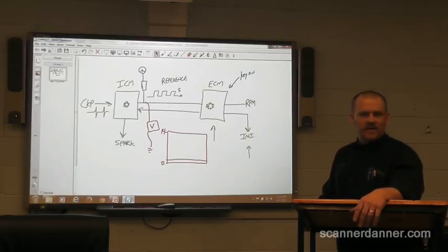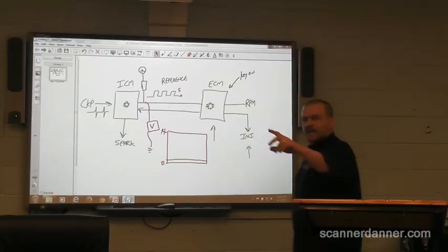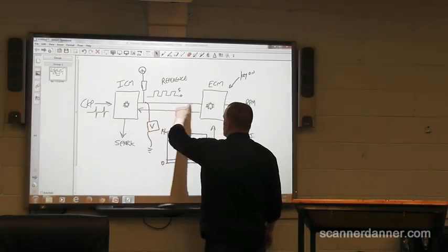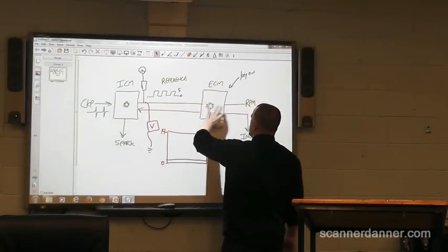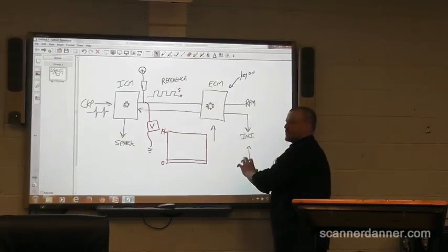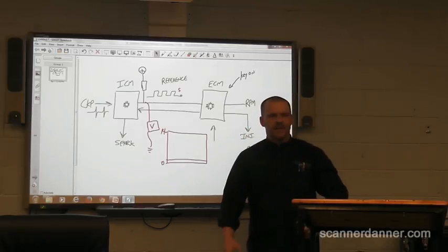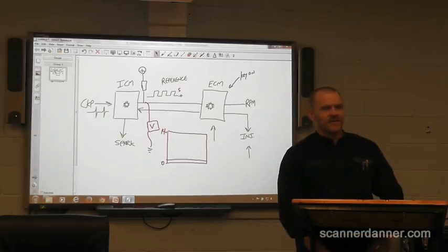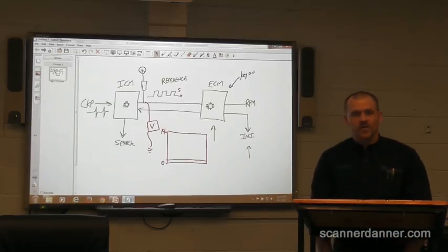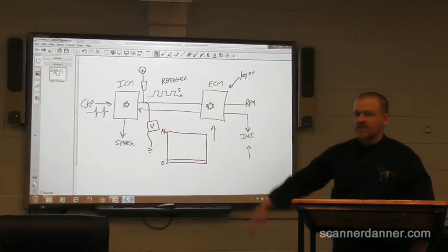The injectors fired. How is my signal wire? How is my computer? How are my injectors that it reacted like it should have? It says they're all good. And so the method would be to replace the ignition module.